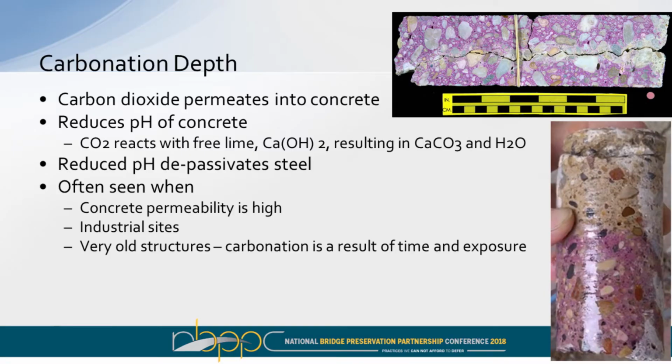Carbonation is something that we don't typically think of first. Chlorides cause the problem first in a deck, but carbonation is an issue to keep track of, especially at cracking. Carbon dioxide can permeate into the concrete and react with the free lime, lowering the pH of concrete. When you lower the pH of concrete, the passivity of steel is broken down and you can start corrosion.